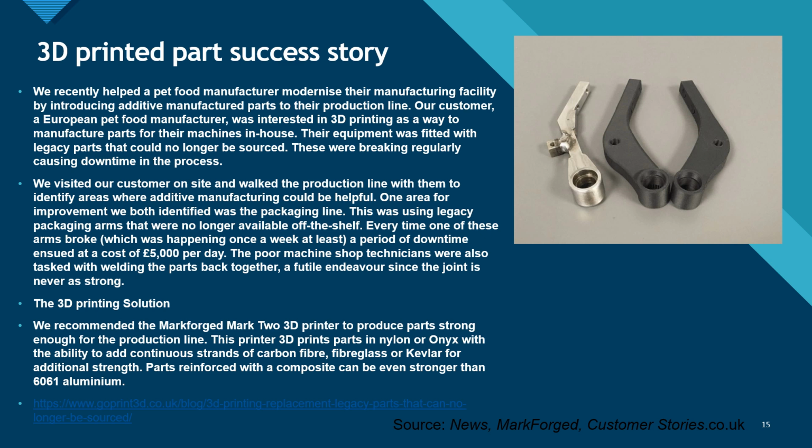The arms, which typically broke at least once a week, would cause a downtime period, costing roughly £5,000 a day. By switching to a 3D printed part, it was easier to maintain stock and create the part out of a tough nylon with reinforced carbon fiber, Kevlar or fiberglass. Such parts, when properly printed, can be stronger than 6061 aluminum.